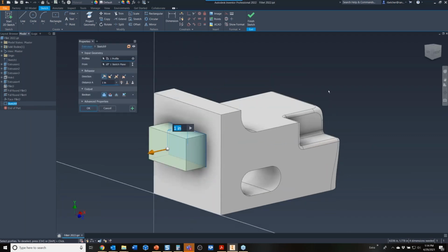So when I launch the extrude command, of course, I see the properties panel appear. Now, in past releases, we all know usually the default for extrusion is a solid body, something either a cut, an intersect, or a joint. And if you want a surface, you usually would go up and you would toggle back and forth between the solid and surface options. You'll now notice there's no solid button up here on the extrusion properties panel.